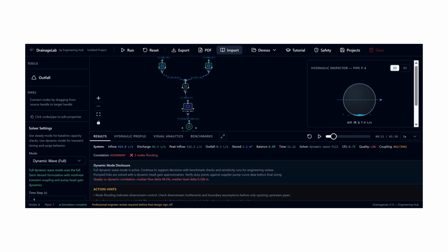We also use a semi-implicit friction update to calculate minor head losses, which is K v squared over 2g, I think. And because it's integrated semi-implicitly, it remains unconditionally stable even during rapid pump startup surges. So basically, as the wet well drains, the pump cycles off at the low level trigger, and it shows the exact drawdown curve.